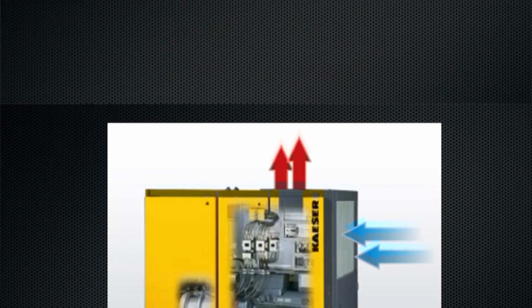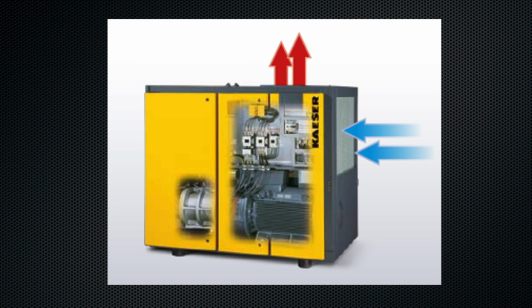So what do you do? You try to get some sensors going so that you know what the pressure is in the system at all times, and you look at where the pressure is going when you're at your maximum load. Let's say at your maximum load, your pressure dropped to 80 pounds. So you go out into the plant and ask everyone, hey, at 2 o'clock yesterday afternoon, did stuff not work because we didn't have enough compressed air pressure? Most of the time everyone says no, everything was fine. And then you know you can turn the pressure of your compressed air system down to 80 pounds and everything will still work.